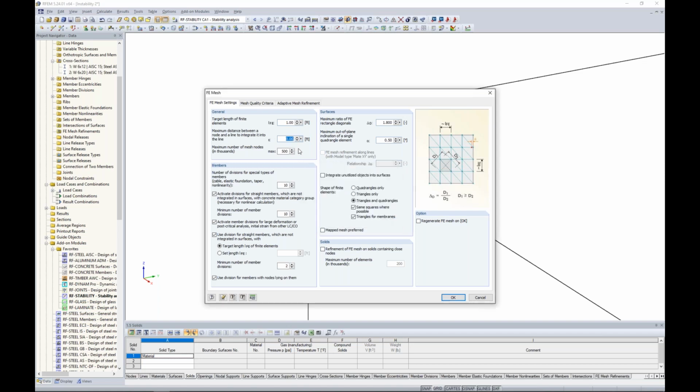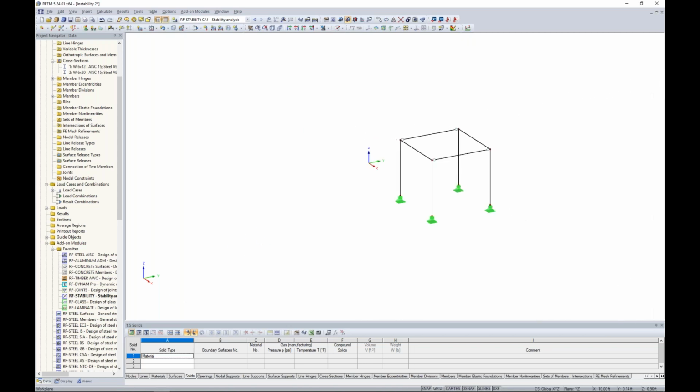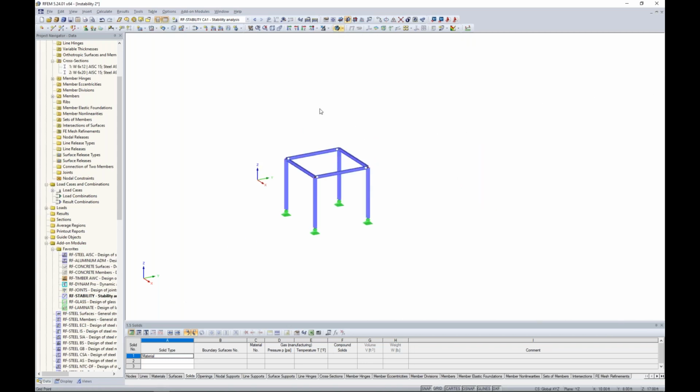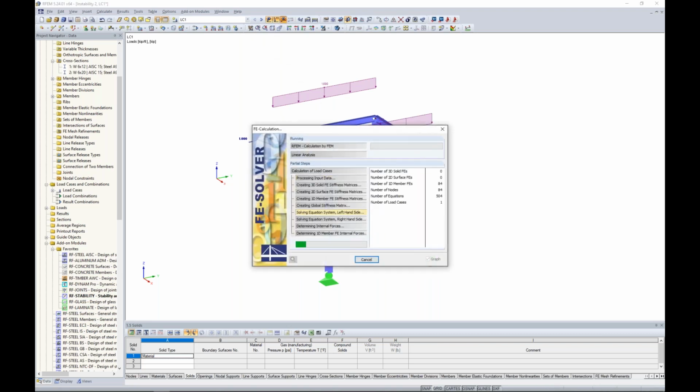So this is the default setting, and you certainly can increase this, but you really need to be careful because if you set this to something too big, you're going to begin to merge nodes together during the calculation that really aren't meant to be merged. So we'll leave this as default because clearly this distance is much greater than 0.003 feet, and all we need to do here is just grab this node and snap it to that column. Okay, so hopefully we've alleviated this instability. What we would do now is jump back to load case 1, remember with those same applied loads, and we'll begin to run the calculation.